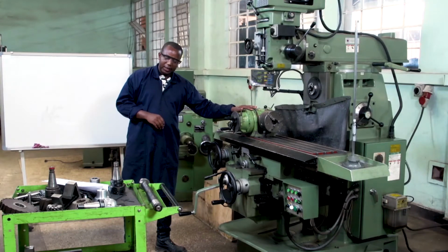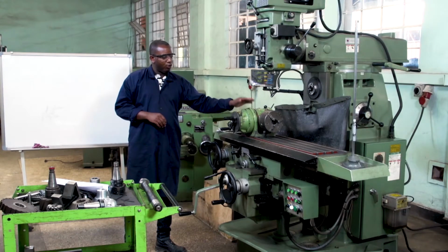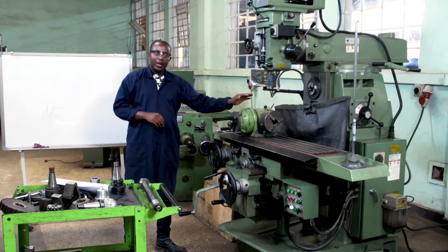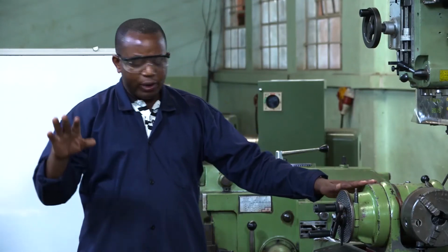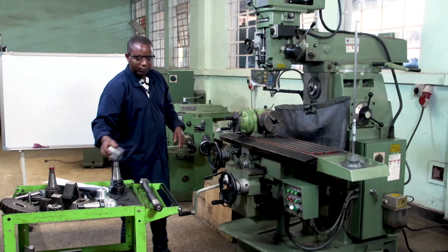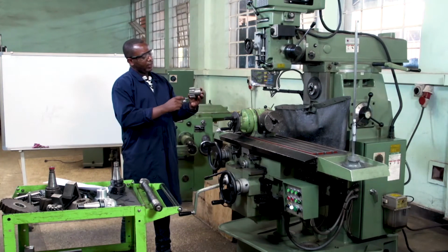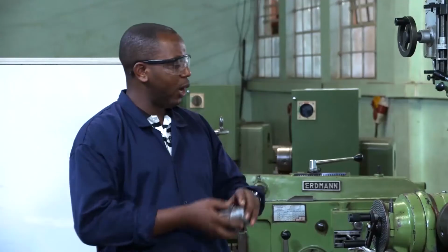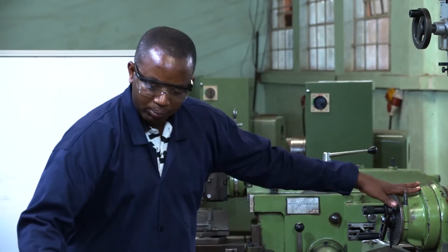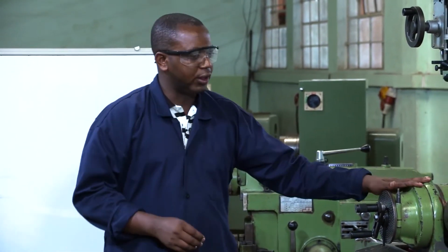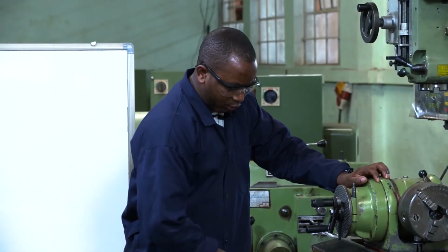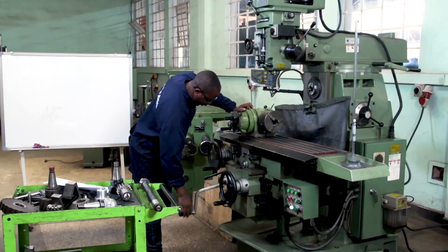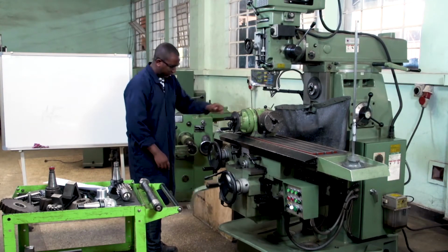The dividing head is used for fixing the workpiece and also to divide it into a specified angle about the spindle axis, which is needed when you manufacture gears. It means that the space between one tooth and the next comes from this dividing head mechanism while being used. So simply, here there are some handles which have to be used.